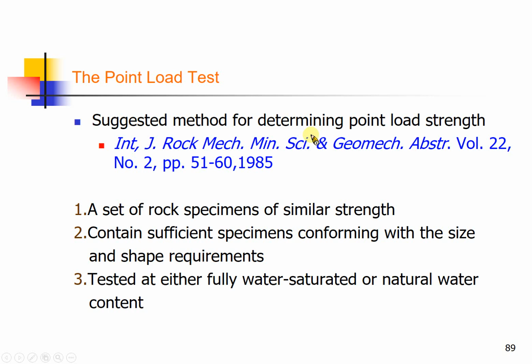Sorry. You say the statement is that you put the point load according to this. Sometimes for homogeneous rock we can put it anywhere. But if it is heterogeneous and we have some big grain size, if you put the point there, it may be very strong and we cannot accept the result in this condition.